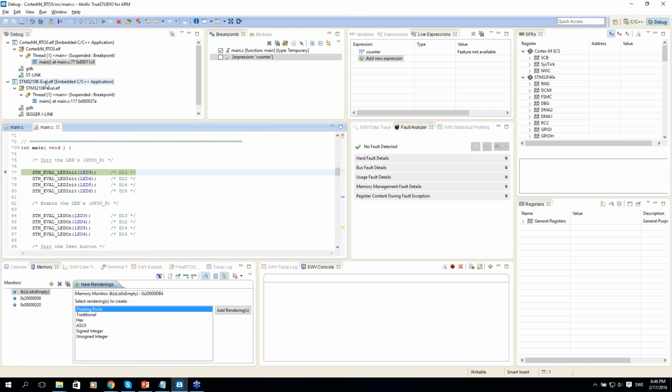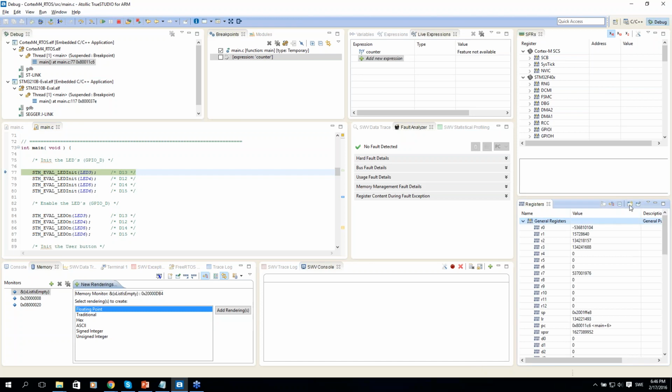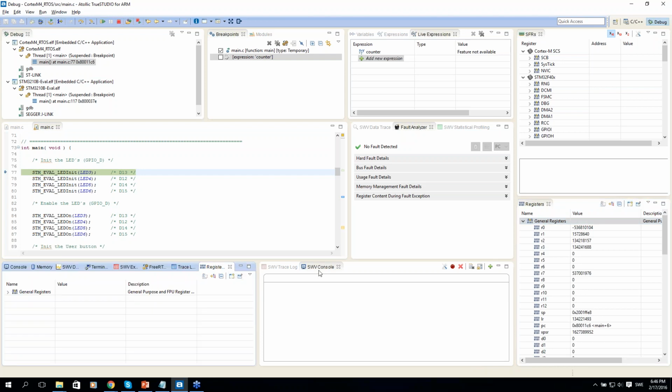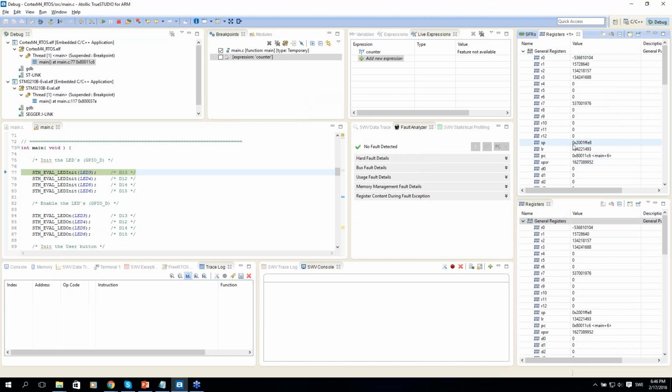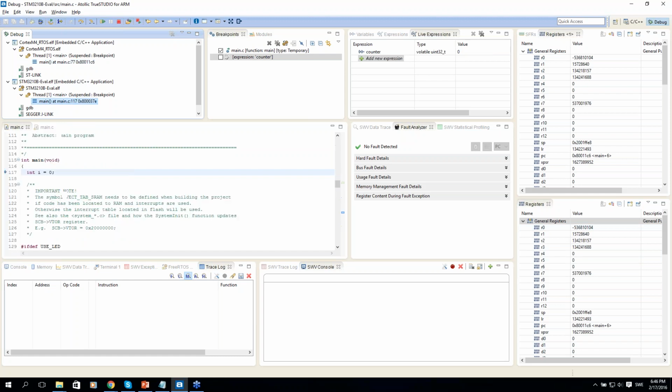It can be kind of confusing, so a cool thing you can do here is to actually open multiple register views, or whatever you're interested in having multiple views on. So I'm going to open a new view here. For people interested in multi-core or multi-processor debugging, this is nice. What is a problem here is, what context am I actually analyzing? If I click here, you see that the CPU core registers have these values. They have that here too. If I click here, both change to reflect this core.